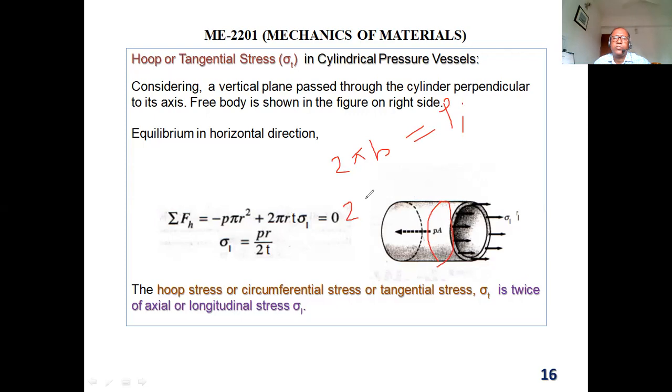And after you pressurize, your diameter will increase a little bit, right? So r plus delta r. So the total peripheral length will be PF. Now you subtract these two. You can figure out how much the radius increased by measurement. So say the radius increased by delta r.